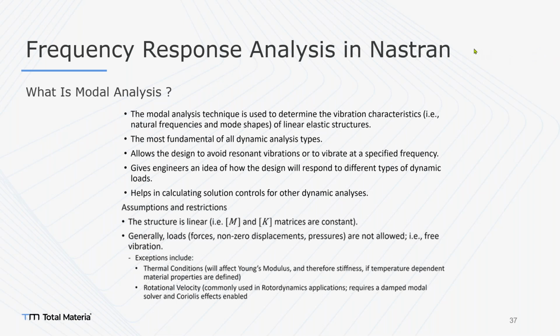The system is considered in free vibration, and it gives us the natural frequencies of our geometry or component, so that we understand its resonance vibrations and can avoid them when we are designing a structure.